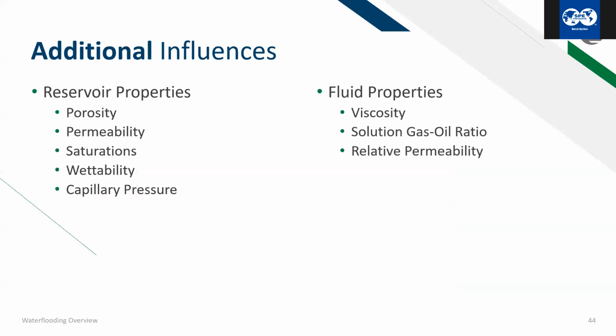And there are additional influences. There are probably more than this. These are just the ones that I thought of when I was making the slides. But you have reservoir properties that will influence your mobility: porosity, permeability, your saturations, what's your wettability, capillary pressures, things like that. And then fluid properties, like we've discussed, your viscosity, if you have gas in the oil, and then your relative permeability.